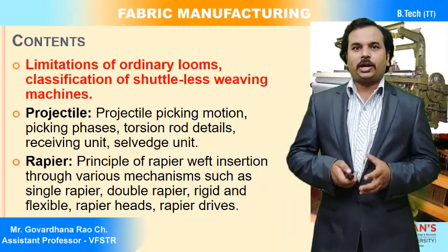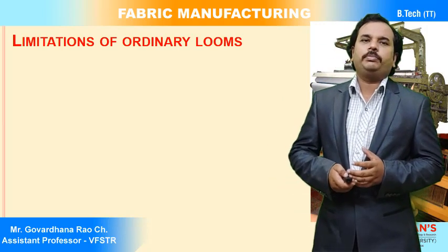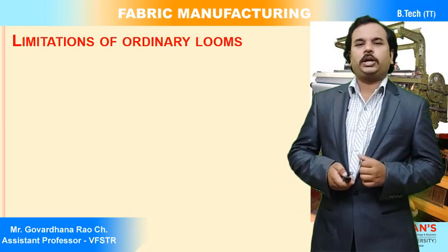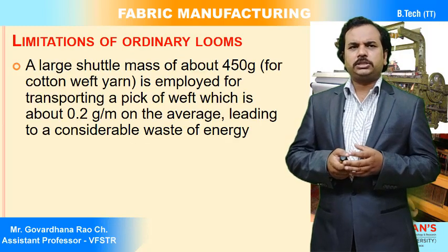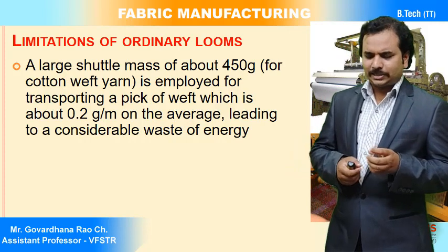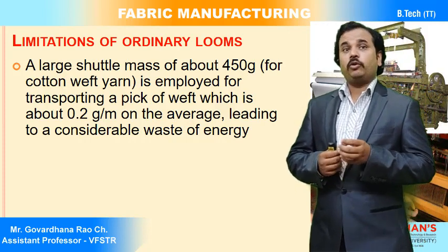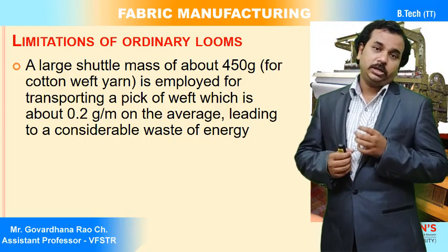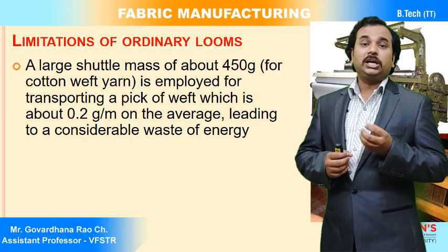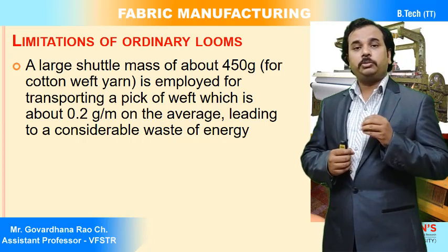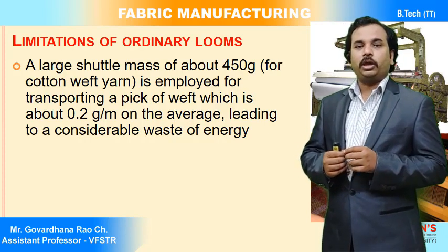Now we will see what the limitations of an ordinary loom are. Most people know them, but we will discuss them one by one. The weight of the shuttle is approximately 450 grams to 500 grams, depending upon the type of shuttle, the type of loom, and the content of the weft yarn package in the shuttle.